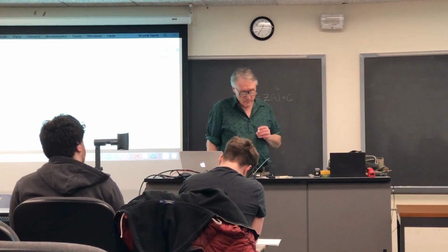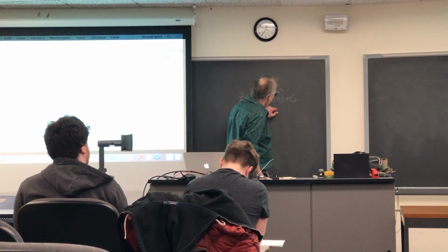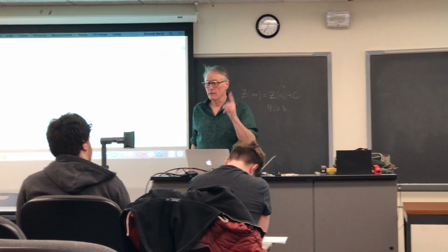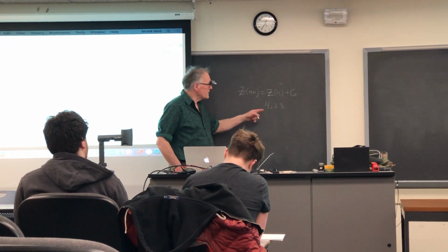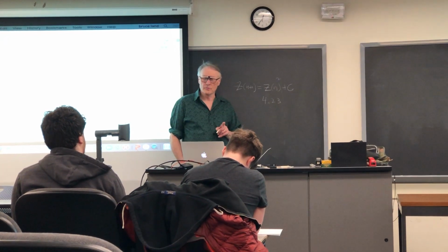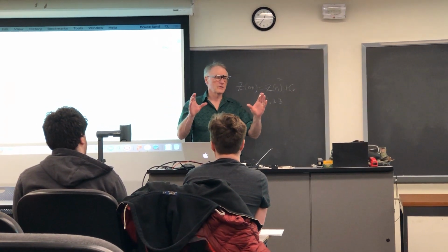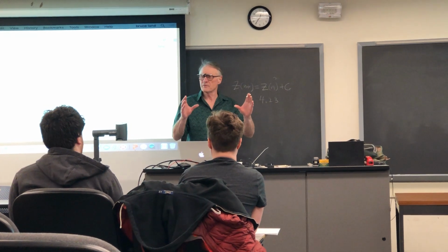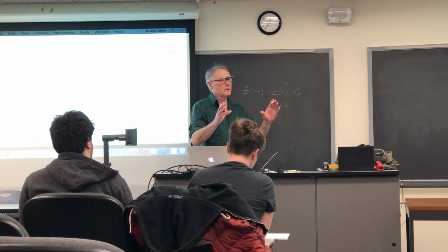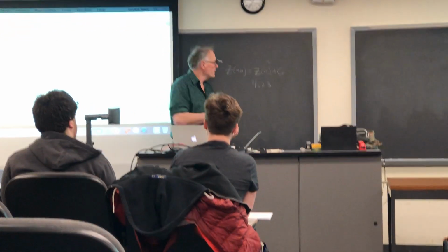And I'm suggesting that you use 4.23 format. It fits nicely into one multiplier. It has enough bits so that you can expect to do about 13 zooms. So you figure if your initial 640 by 480 image is going to use about 10 bits of precision on X and Y, then we can zoom about 13 times before we run out of pixels.